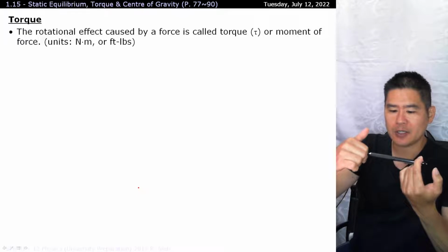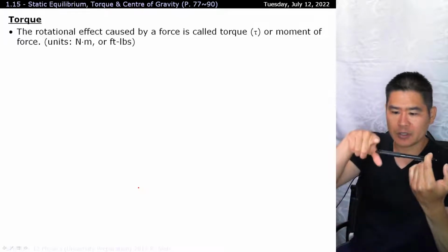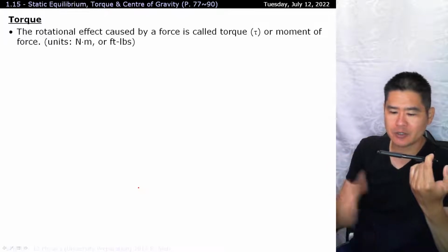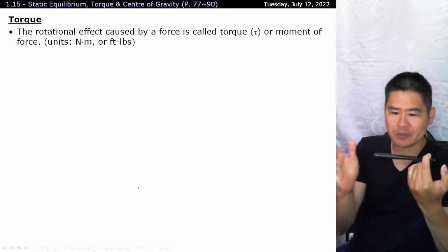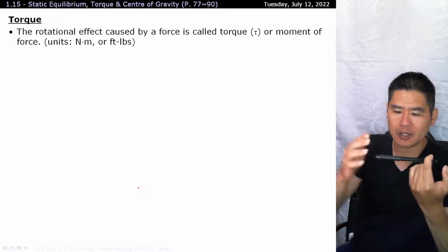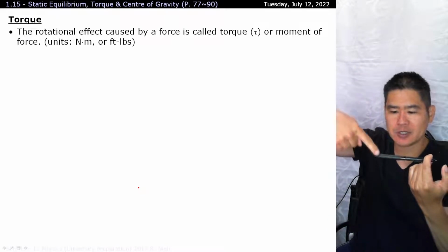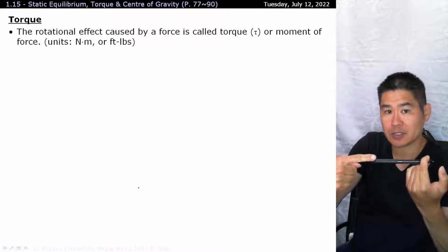All right. Now, there are different ways of cranking. You can directly push downwards, or you can push at a diagonal, or you can try just bashing at it. And you'll notice if you try bashing at this crankshaft, you're not going to get any useful work done. All right. At 90 degrees, you get the most optimal work. Anything less than 90 degrees, it diminishes down to the point where you get to 0.